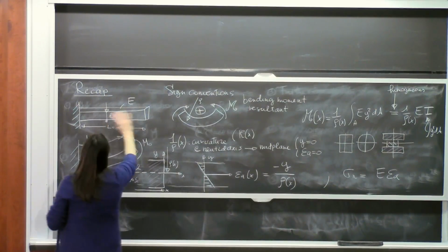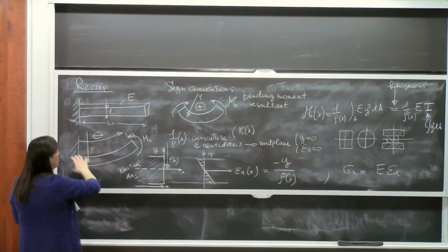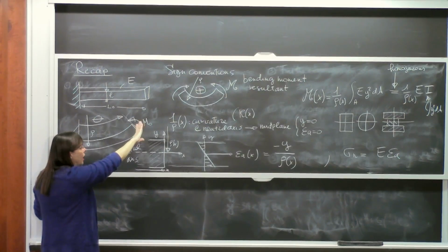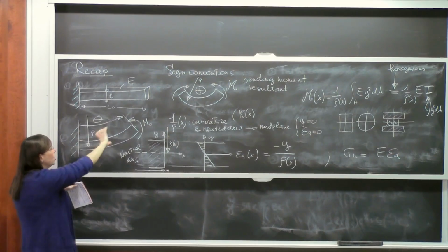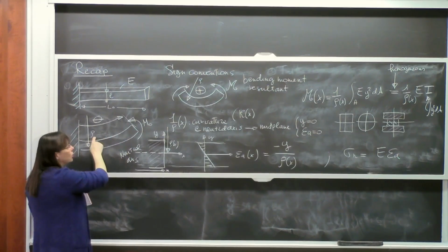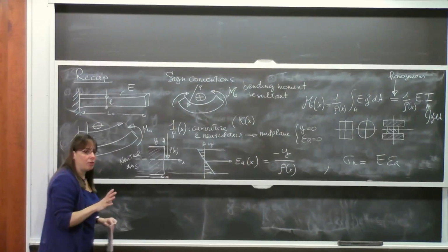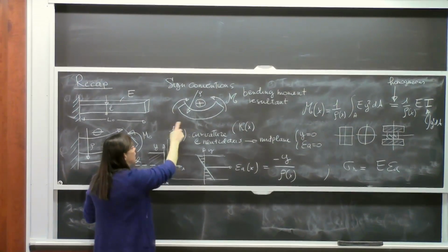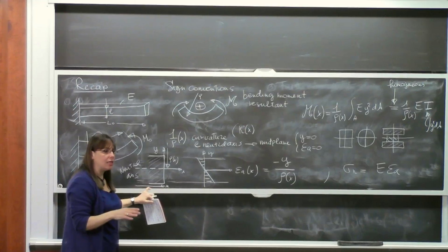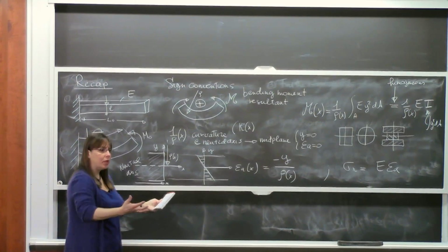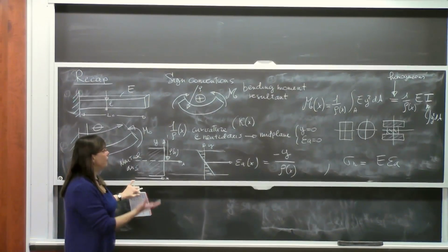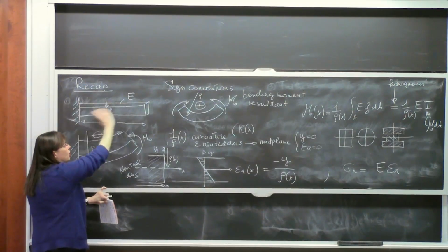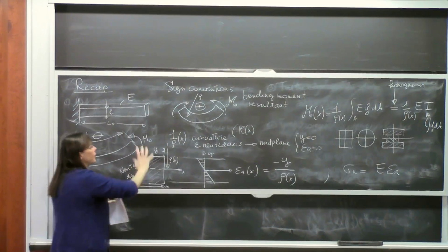So our beams are slender, and we started with a homogeneous beam, and we just loaded it with a moment at the end, M0. And under the effect of this end moment, the beam curved up, with a certain radius of curvature rho. So we defined the deformation of the beam in terms of the inverse of the radius of curvature. We call this the curvature, and we take the curvature as the measure of deformation. Things that have large curvature are very curled up, with a lot of deformation. Things that have low or zero curvature are in this configuration here. The radius goes to infinity, the curvature is 0. And then as the beam curls up, the curvature increases.